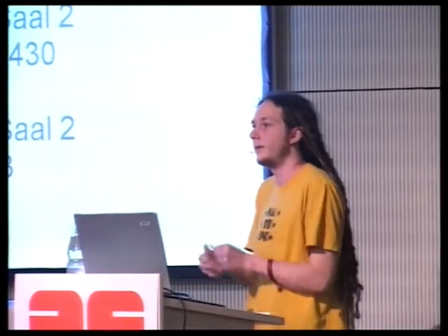So I printed out the disassembly of the code. And then for a couple of days I went through and I annotated the different pieces of it. The lecture that I'll be giving on the 29th in Sal 2 on repurposing the msp430 describes the tools that I used for this. I've got a Perl script called msp430 static that lets me, say, identify every function that contains code that writes to a particular I/O port.